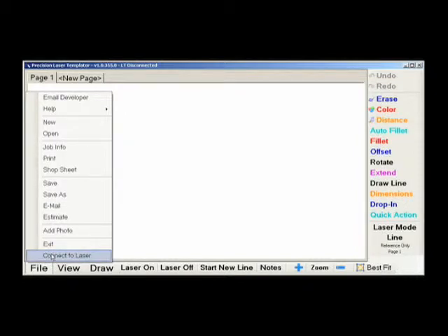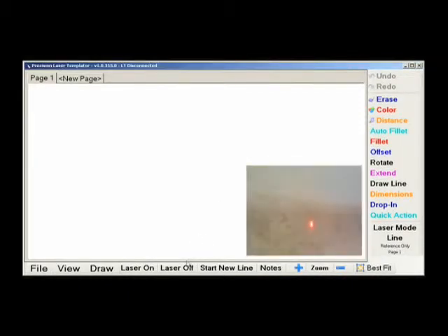The most common reason for the laser not to be connected is if the laser is left alone and the tablet PC sits too long. This can then send the tablet PC into standby mode where it will go to sleep. Just to note, when you first turn the laser on by flipping the on-off switch on the black box, this sets your orientation. The laser should be pointed in the direction you want to have it be the top of your drawing. Clicking Laser Off will simply turn the laser off.